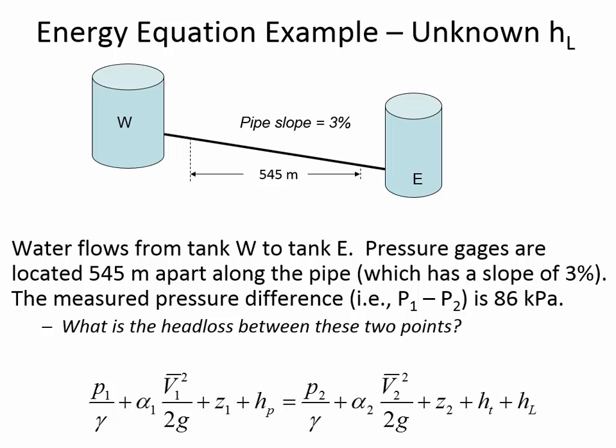And then in Bernoulli's equation we had a pressure head term, a velocity head term, and an elevation term. And many of those are here, but with a few exceptions and adjustments. So the pressure head term is the same. In the velocity head term, if we're looking strictly speaking at the full-fledged energy equation, then we can use a kinetic energy correction factor, which adjusts for the fact that here in the energy equation you'll notice that there's a bar over the velocity. So it's the average velocity squared.